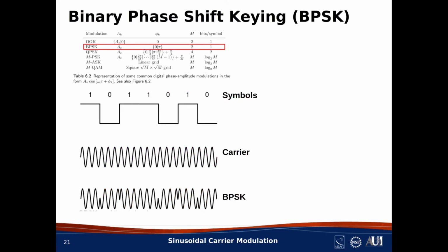A very common digital communication scheme is binary phase shift keying, abbreviated BPSK. BPSK is an M equals 2 scheme where the bits correspond to one of 2 opposite phases of the carrier. So, you can tell which bit is being sent by determining the phase of the carrier. And here's the constellation diagram for BPSK. Note that the BPSK signal always has constant magnitude, so the symbols are shown as having equal distance from the origin. And the symbols have opposite phase, so they're drawn as being on opposite sides of the origin.